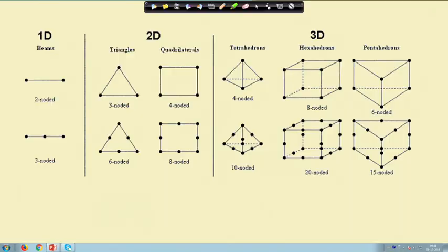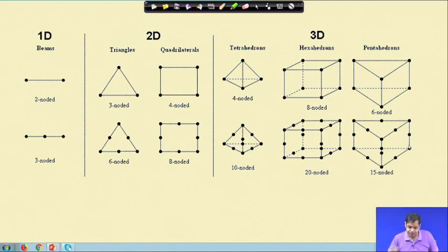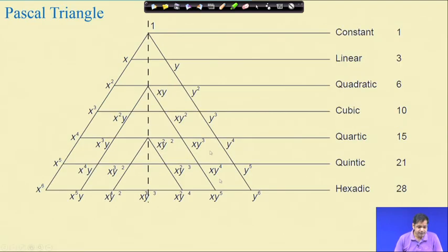Okay. Now, in 3 dimensions you can have other degrees of freedom like this, but the essence remains the same. Once you have the degrees of freedom, approximate them, give a function representation of those degrees of freedom through which we can get the values at any intermediate point, substitute that in the expression and get the corresponding stiffness matrix. Okay. Now, this is important.